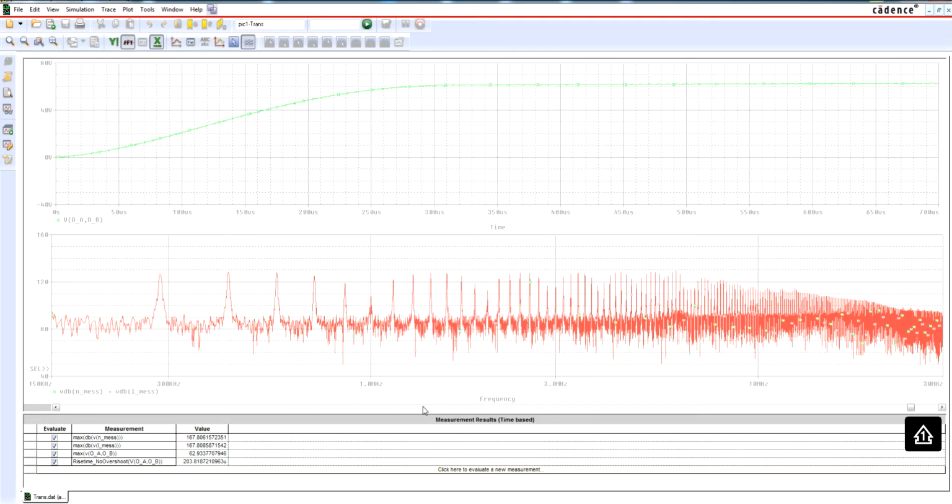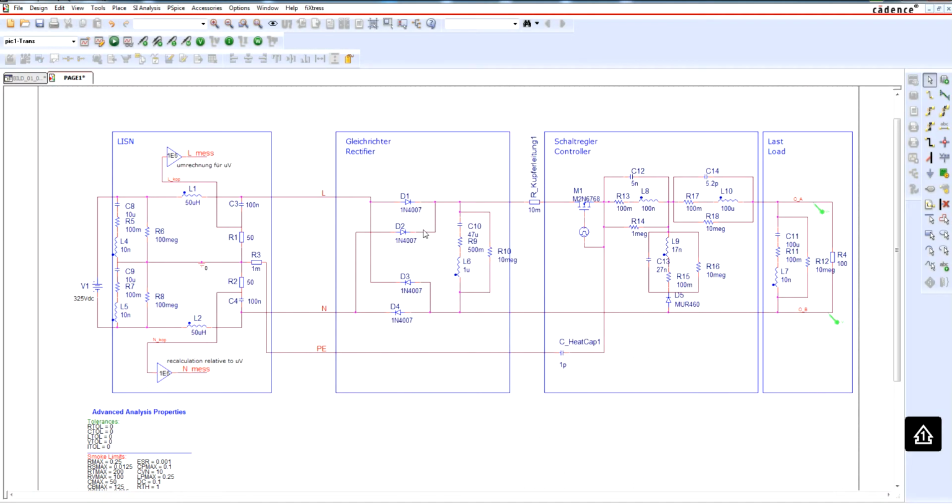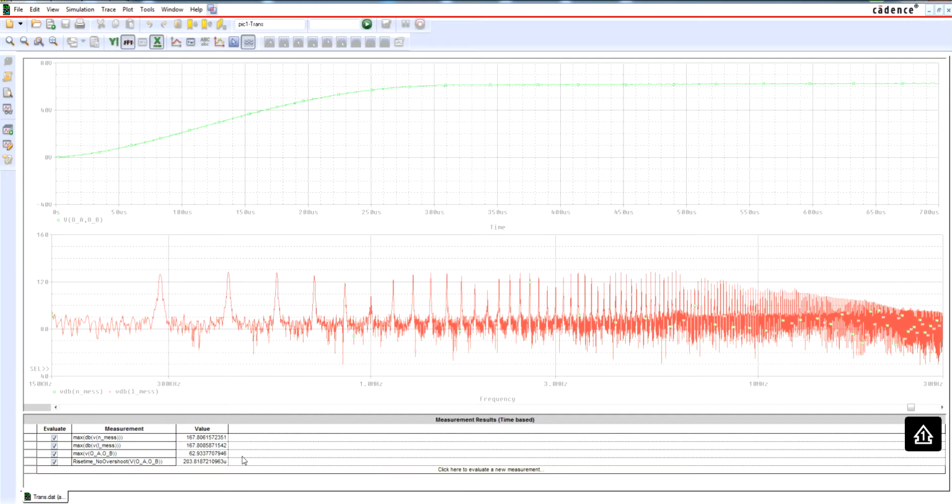The goals or the requirements or the challenges for this circuit are the maximum value of the electromagnetic interference, also the output voltage, the maximum value, and the rise time. The rise time is between the 10% here and the 90% here. Why? Because sometimes some requirements, this rise time must be really fast, or it can be slower. And I want to analyze in terms of the tolerances of my components, which variation I'm going to get, and if I am inside of my requirements or not.